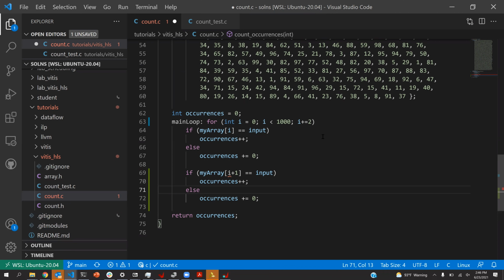What if it has 2 address inputs? Okay. So yes, some memories, like the BRAMs on your FPGA, are called dual-ported memories. They have 2 sets of these signals, 2 address, 2 read, 2 write. So you could read 2 things at once, or you could write 2 things at once, or you could read 1 thing and write another thing.